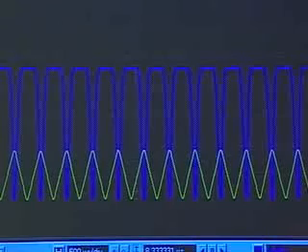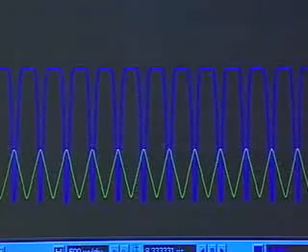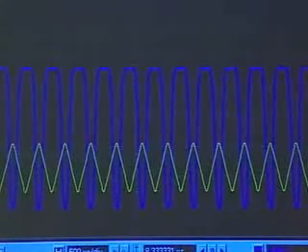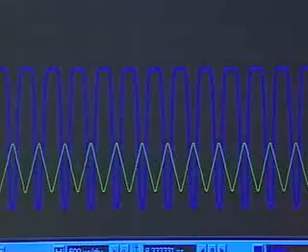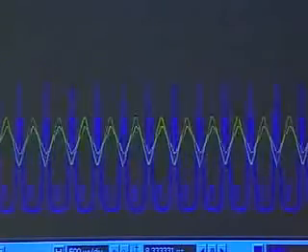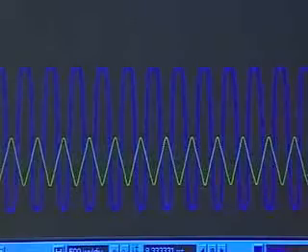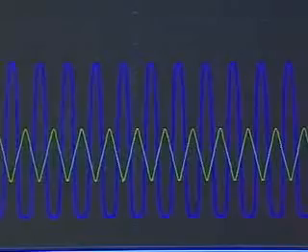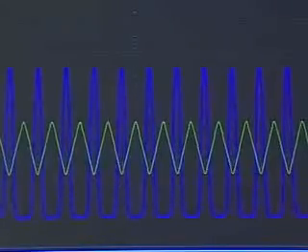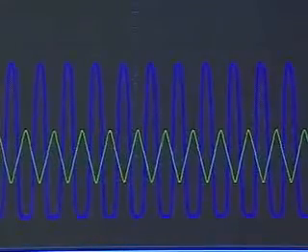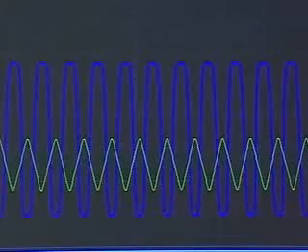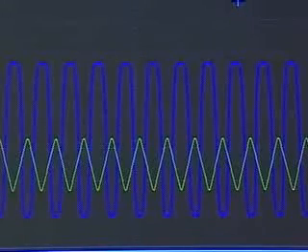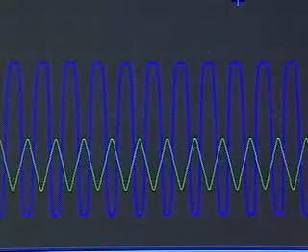So what I'll do here is apply some suitable offset. Is this the one? Yes. We want to switch to, yeah. So you can see this is the input. You can see I'm applying an offset by boosting up the input. Okay, so I don't have clipping happening at both ends, but I get something, and I get amplification.